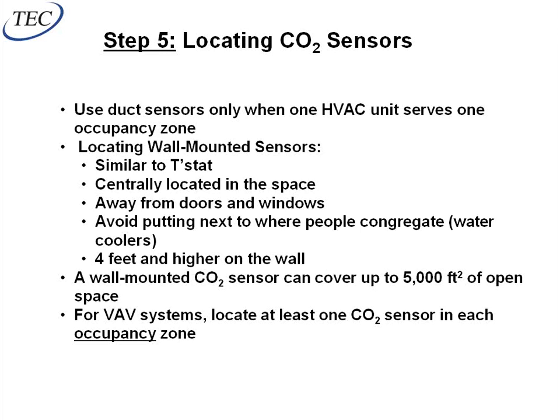When you put it in the space, you typically mount it in the places that you mount a thermostat. So I want to stay away from windows and doors because windows and doors tend to have a solar effect on the thermostat reading. Well, for the CO2 sensor, it tends to be places that drafts are likely to happen. So I don't want to have it there because then I'll get a false reading. I don't want to put it places that people are going to hang out, like the water cooler or the copy machine or anything like that. And I want to have it in the breathing zone, which typically means between 4 and 6 feet high